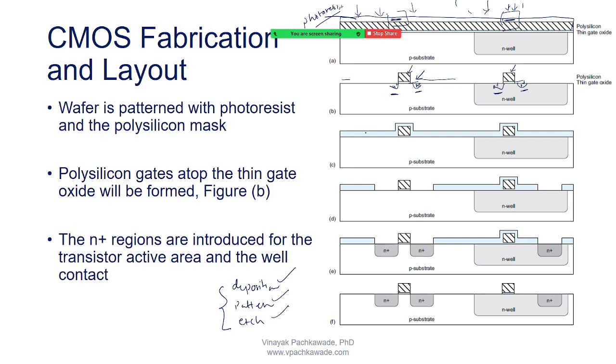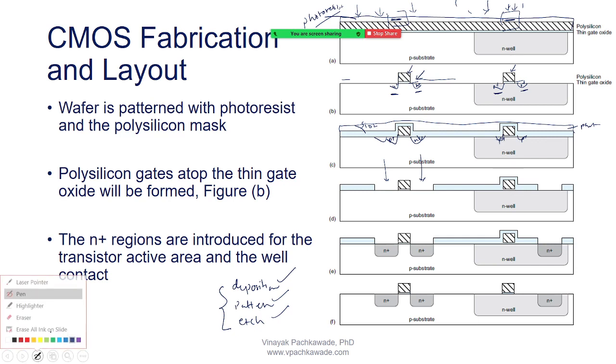So what I do is that this is SiO2. All over the wafer I will deposit this SiO2. Then on top of it again I will have a photoresist. Then where I want the N plus diffusions to be fabricated, somewhere in these areas, just next to the gate, right? Because the transistors are there, here will be N plus and here will be N plus. You see now this area, these diagrams, where I want these transistors to be fabricated. Okay, let me draw it this way.